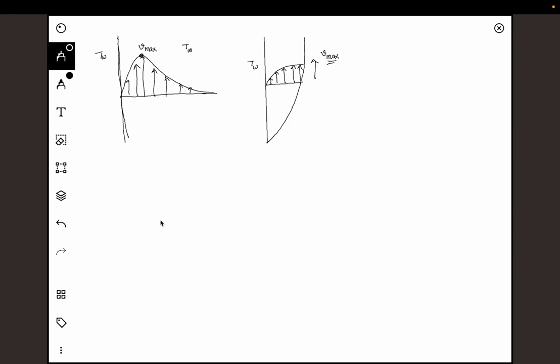So the same assumptions, whatever we have, let's say it is a 2D steady problem, all those assumptions are there. The question now is you have to compare the heat transfer coefficient here and here. Let's say this is H free and this is H forced. In order to do this, you don't have to do anything. Essentially, it happens naturally. As long as the wall temperature is maintained, this convection will always happen. Here, however, in order to maintain this Vmax, you have to externally put, say, a pump, fan, or blower to actually blow the air across, because there will be some finite frictional drop here. In order to overcome it, you have to spend some energy here.